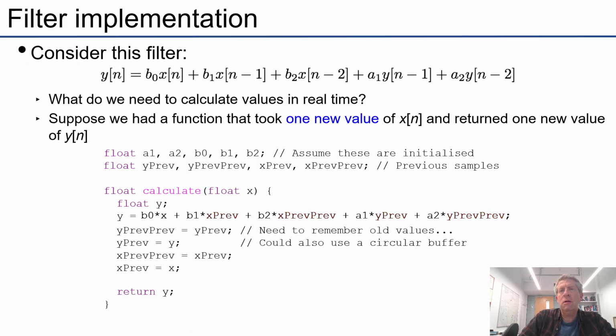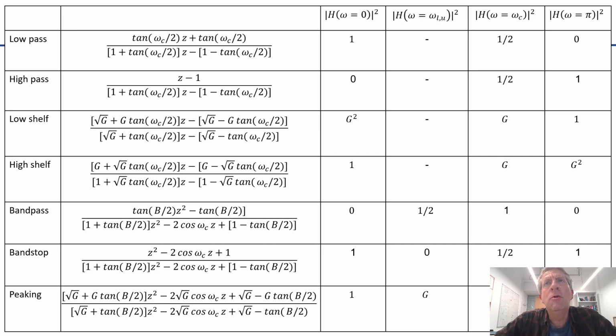Here they are. So a low pass filter, you have the center frequency expressed in a range from say 0 to pi, I think it is, for omega c. And the low pass filter only depends on that one parameter for the lowest order, which is first order. High pass similarly only depends on omega c, so that cutoff or transition frequency.